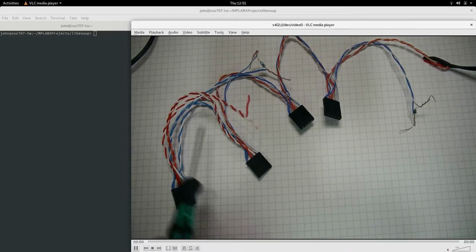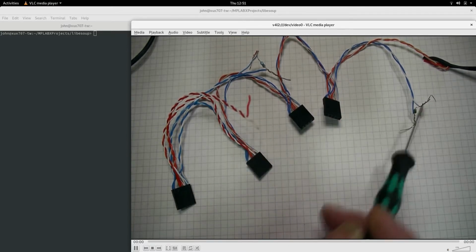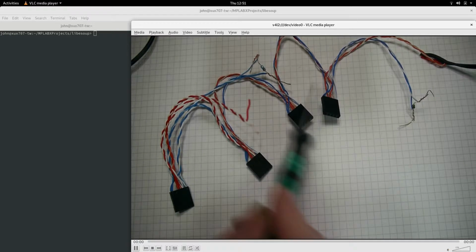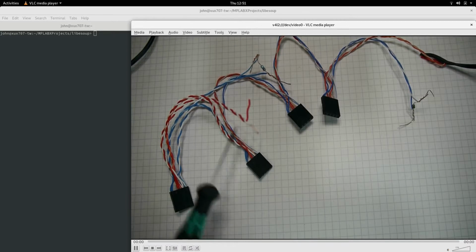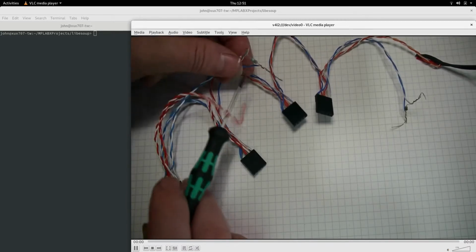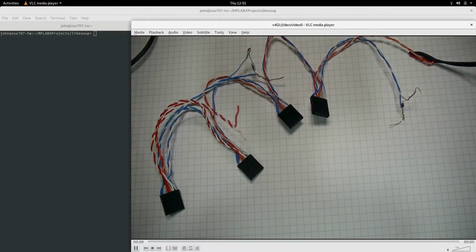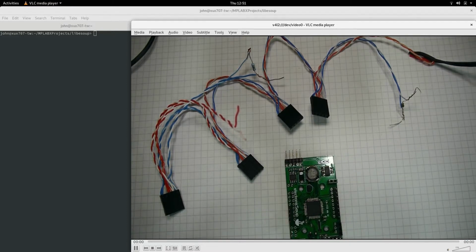And this is my little test bus with 4 nodes, or positions for 4 nodes. The orange and white and orange are the power and ground, and then the blue pair are my CAN bus, which is terminated on both sides with a very simple 120 ohm resistor for termination purposes. Modbus was a master-slave protocol, and CAN bus is a multi-master or peer-to-peer network where anybody can transmit at any time.